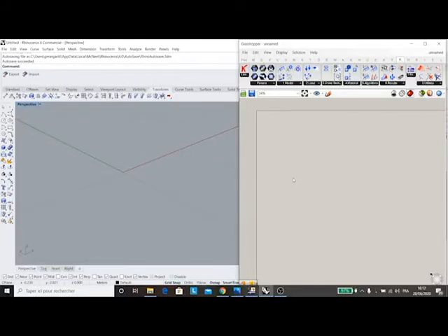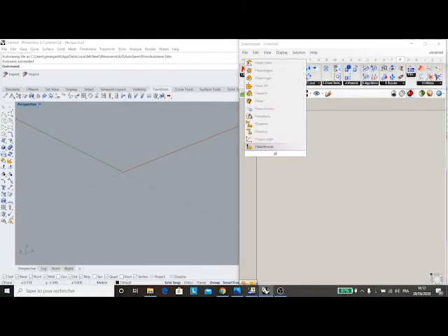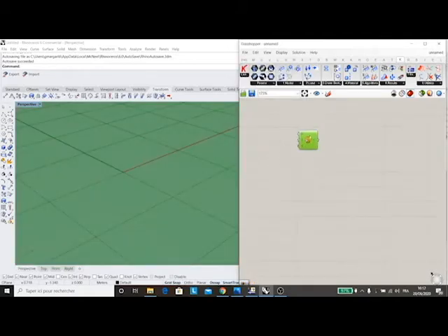This is your first Karamba tutorial. So when I want to analyze my geometry using Karamba, the first thing I do is set my Rhino model in meters. I then create, ideally, a parametric geometry inside Grasshopper. In this case, I will make a very simple surface